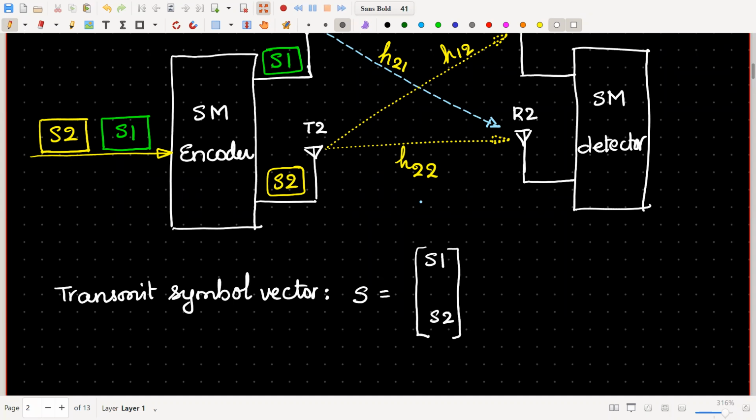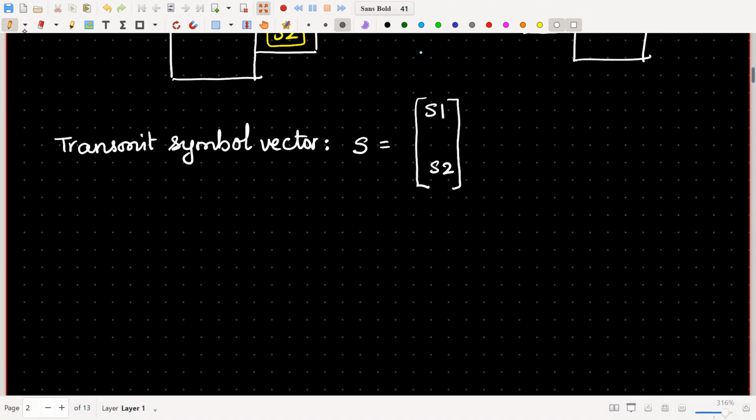And also you have the channel matrix, the radio channel, RF channel matrix. See, you're multiplexing the channel, you're multiplexing the space. That's the beauty. Therefore you're transmitting symbols individually without any interference, because you have certain spacing between antennas. So you can achieve simultaneous transmissions over the same bandwidth.